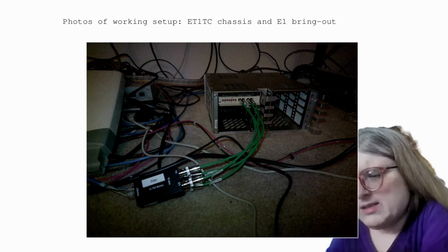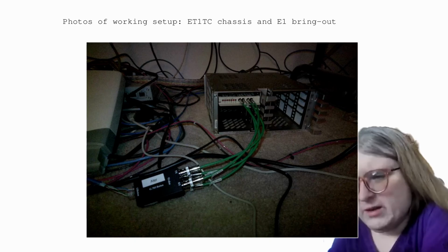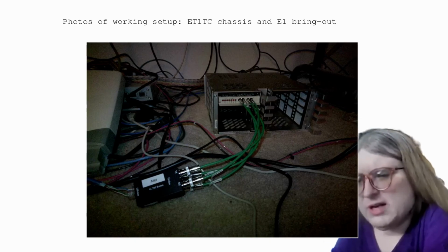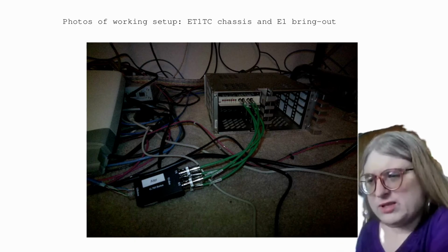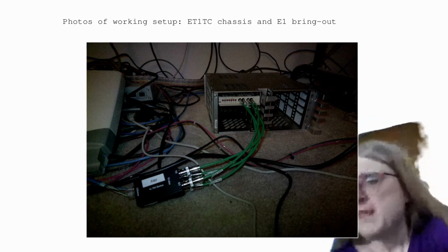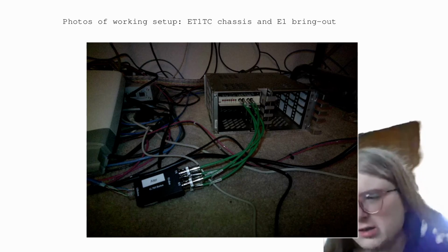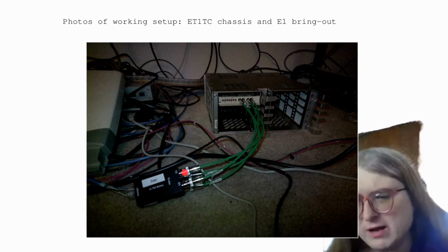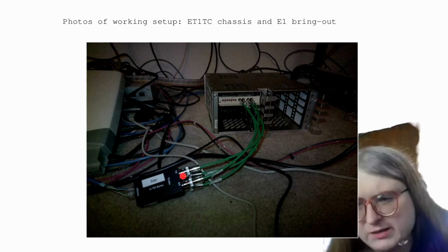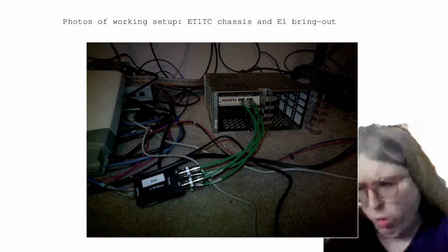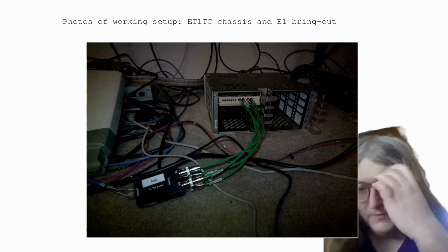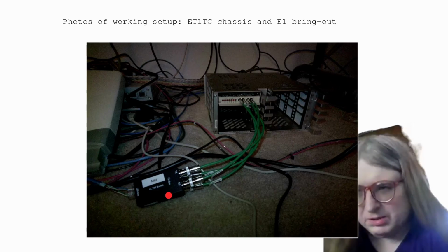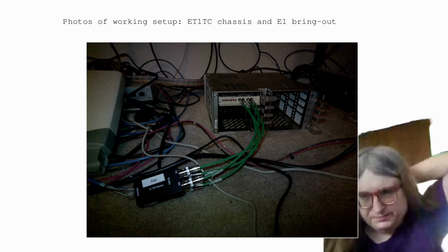When I connected it like this, the LED on the ICE1 USB would flicker, because there's an LED that turns green when it receives a good signal on the E1 port. In coaxial 75 ohm loopback, it would just intermittently flicker on and off on one side.